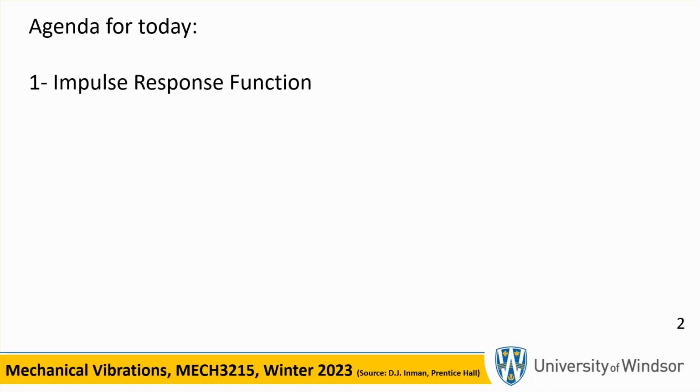The first 3 weeks of the course, we looked at the free vibration of a mass spring damper system, a single degree of freedom system. And now, obviously, this could have been translational, this could have been rotational, this could have been a very complicated problem that you idealized as a single degree of freedom system, and it really boils down to the mother of all equations, which is m x double dot plus c x dot plus k x equal to 0 for the first 3 weeks.